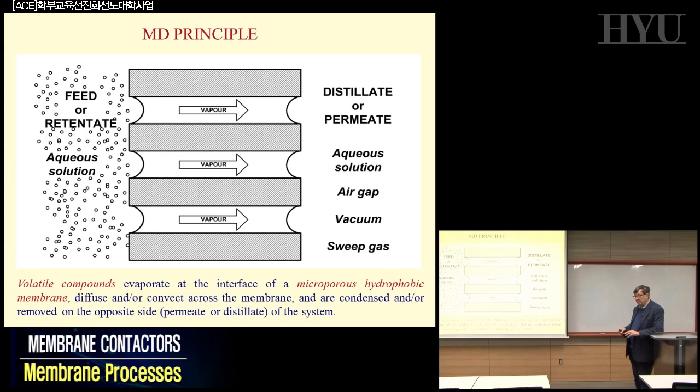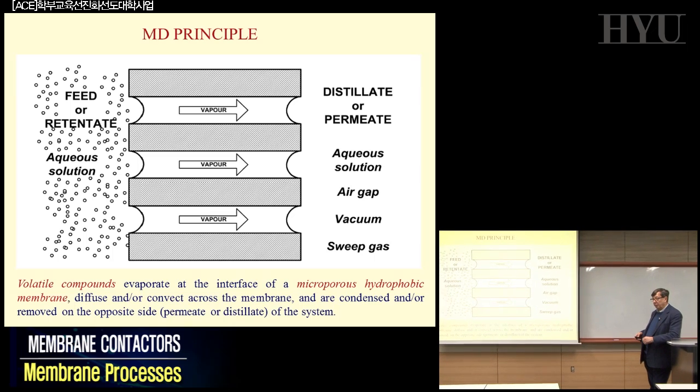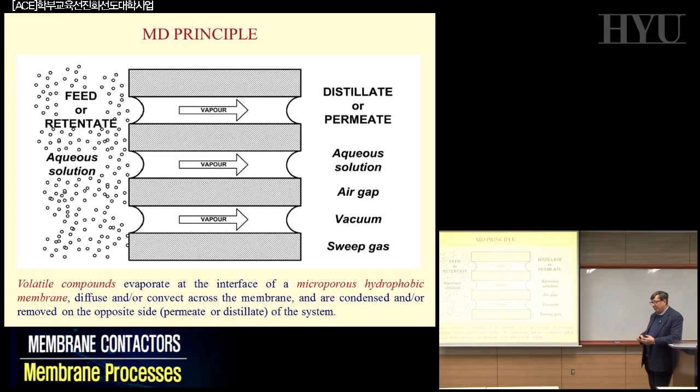This kind of unit is today not so well present at industrial level as the ones we have been discussing until now. These are all new membrane operations, which however are becoming more and more interesting day by day. First of all, because they are able to redesign basically most of the unit operations of process engineering in a way much more appropriate to the logic of the process intensification strategy.